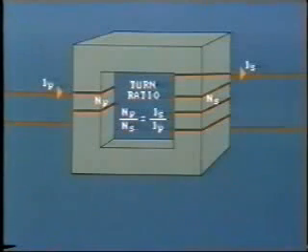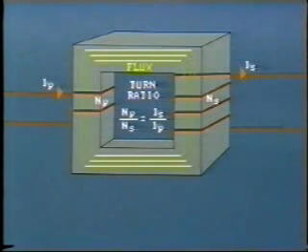For the relay, the most important aspect of the CT is its accuracy in reflecting the current at fault levels, which may be at least 10 times normal load current. Now, CT performance. In an ideal CT, we just saw that the ratio of primary to secondary current is the inverse of the turns ratio.